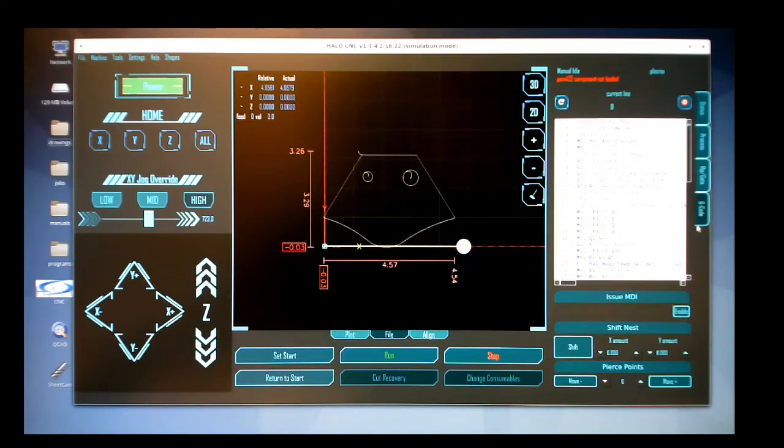The G-code tab allows the operator the ability to see G-code in real time. It also allows the operator to start from the selected line of code. Plasma communication as well as tool selection is also visible. To reset the G-code, hit the reset key. To clear the program, hit the clear button. This will clear out all G-code that's loaded in the system.